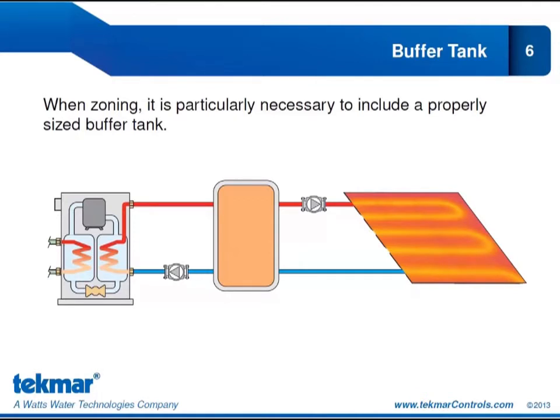If a buffer tank is not needed, then it is important to do hydraulic separation. So to use some closely spaced tees or a hydraulic separator so that we ensure that we are separating the flow from the heat pump from the flow to the distribution loop.